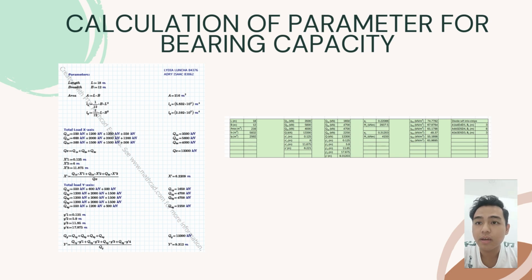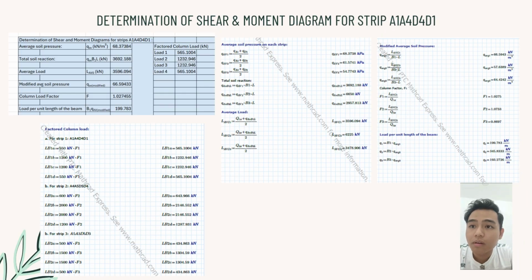And the next part is the result. The soil pressure at A1 is 74.77 and at A2 is 67.97. The soil pressure at point A3 is 61.17. At D3, the soil pressure is 48.37, D2 is 55.16, and D1 is 61.96. After the raft is divided into 3 strips,